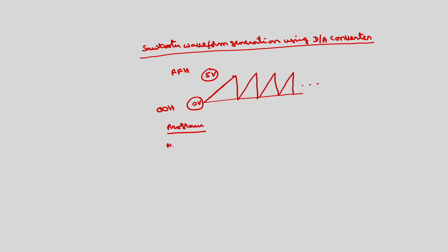we have to program port A as an output port. For that, move AL comma 80H, out FFH comma AL. This will program all the ports as output ports. Now I will take move AL comma 00, then I will output onto port A, whose address is FCH.